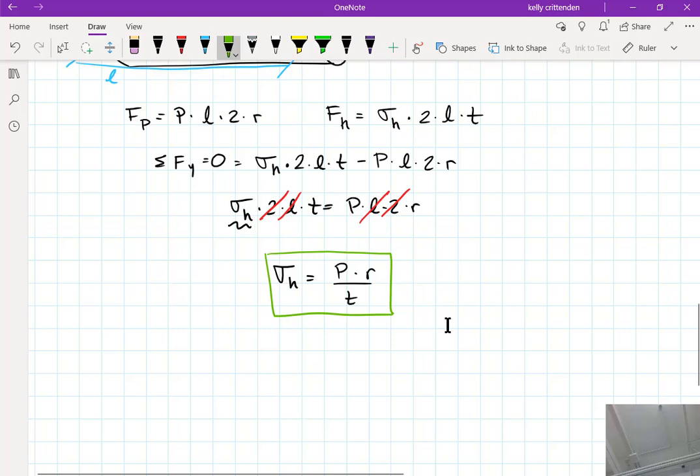So these are super simple equations to work with. The only tricky thing is that the cylindrical pressure vessels do have the 2 different stresses, so you have to be sure which one you're solving for. If you're doing some kind of design or failure analysis, then you want the hoop stress. And technically that R is the internal radius. So a lot of times you might know the outer radius. It is a thin-walled pressure vessel, so the outer radius and the inner radius are really close to the same number, but technically they are different numbers.